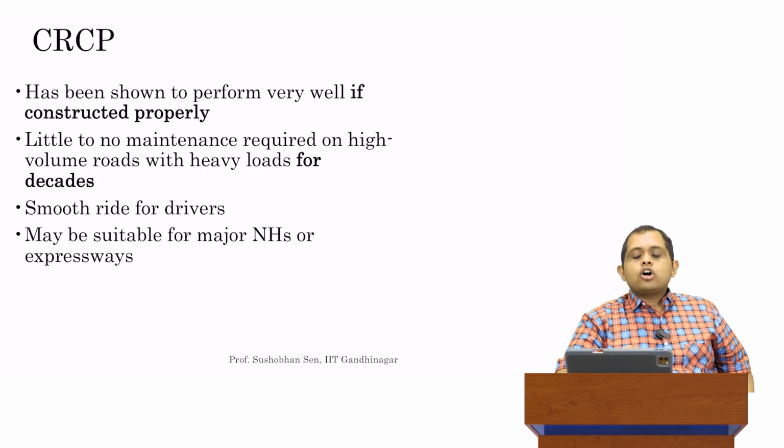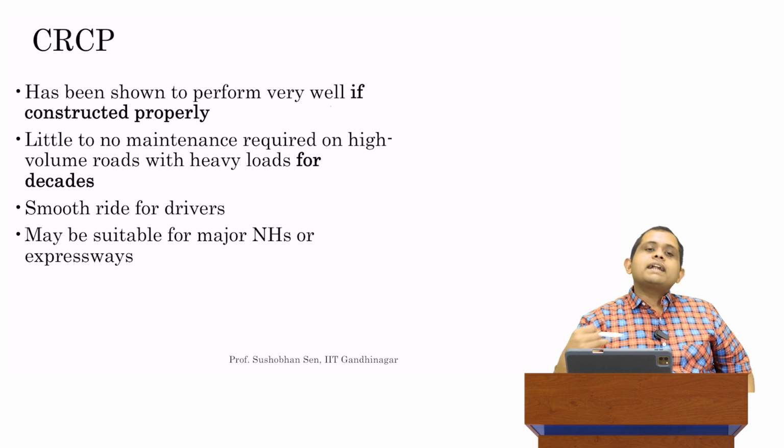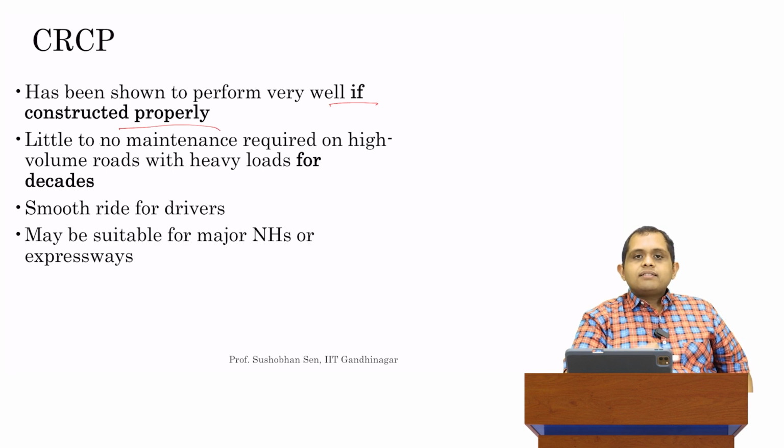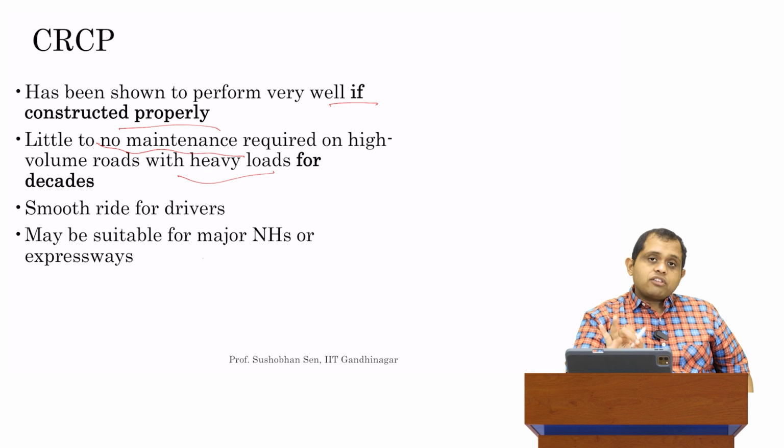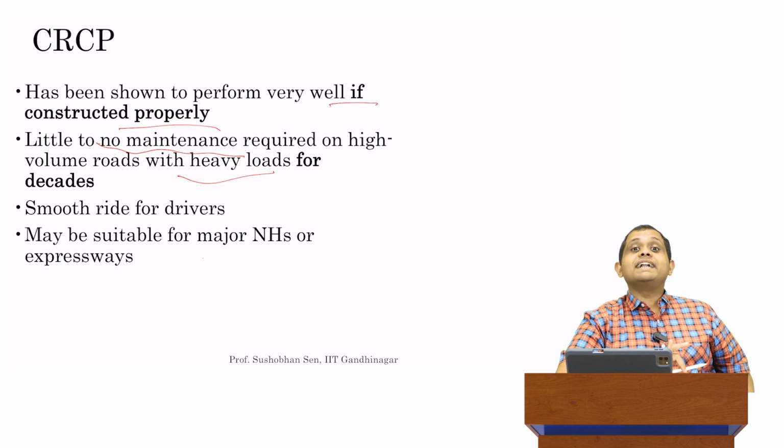So CRCP is not used all that often, but there are plenty of examples around the world, including in India, where CRCP has been used. It has been found that if constructed properly, and that's always a caveat which I add, CRCP has shown exceedingly good performance with almost no maintenance required on high volume roads with heavy loads, the most difficult type of roads to actually design. A lot of heavy trucks on the roads. For such roads, it has been found that CRCP can have almost no maintenance for decades.